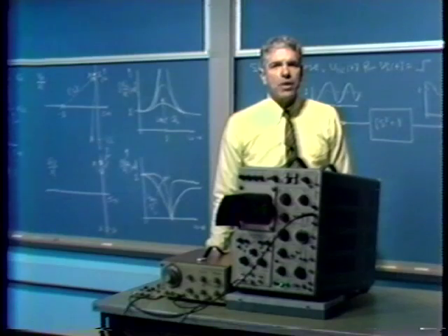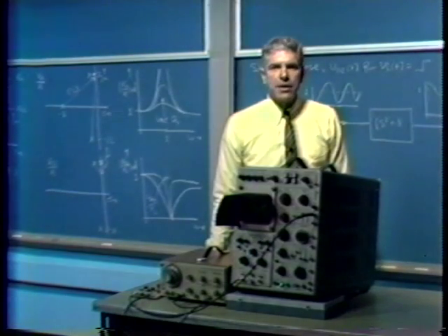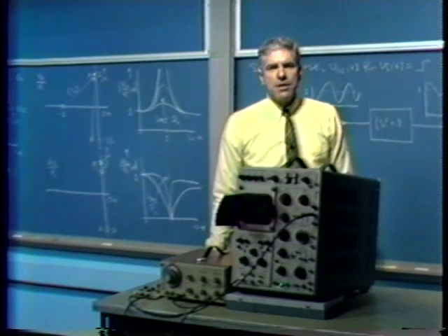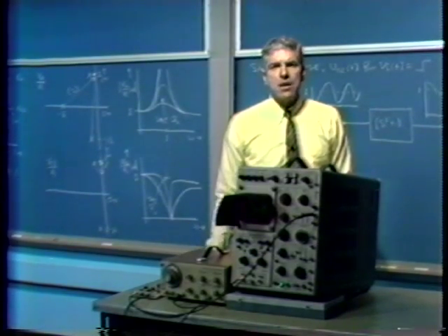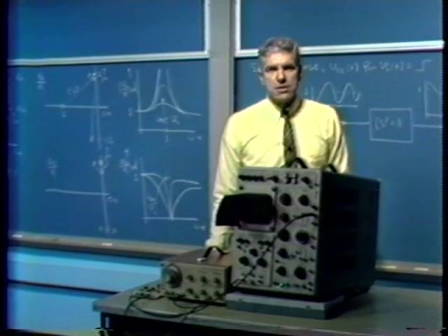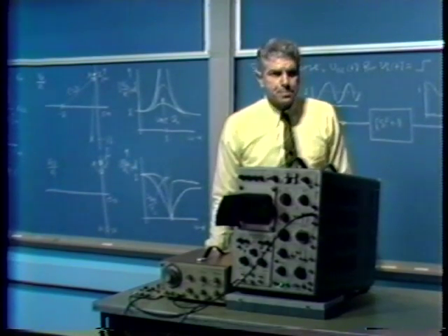However, if we were very careful and had a high gain amplifier and very precisely adjusted the T network, we'd be able to get very, very sharp nulls out of the rejection amplifier. This offers a good way, for example, to build a filter that eliminates a particular disturbance, possibly 60 cycles from a setup where that's a disturbance.